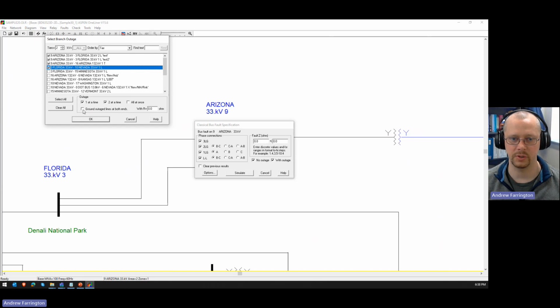So you'll hear the term working between grounds. That's what they're saying, is that there's a ground over there and there's a ground over here, and we've got to stay between those so that we know that the equipment is dead. And then if somebody were to accidentally energize the line, hopefully the fault current goes into the ground instead of a person.